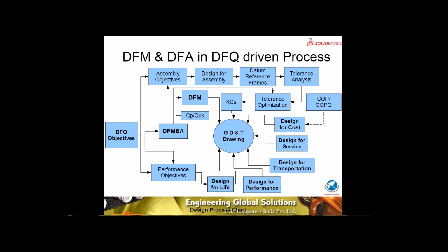This is where leveraging the CP/CPK of the processes, or dictating minimum process capability as a part of the process, helps us in understanding the prioritization of the design for manufacturing and assembly considerations when we are releasing the drawings.